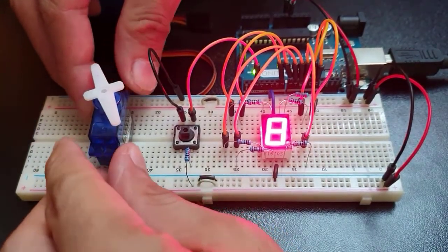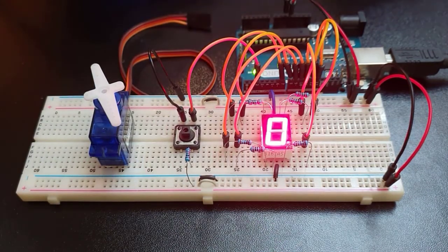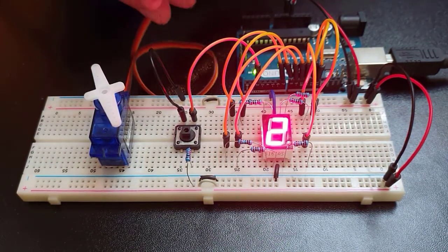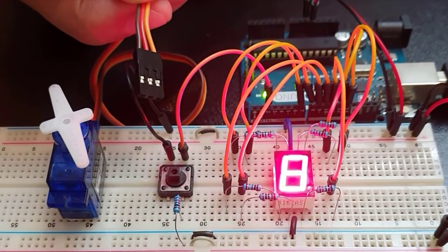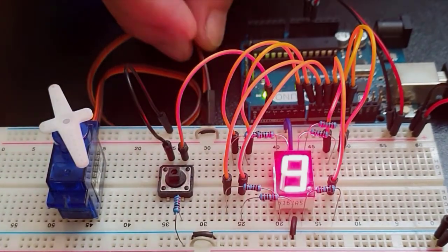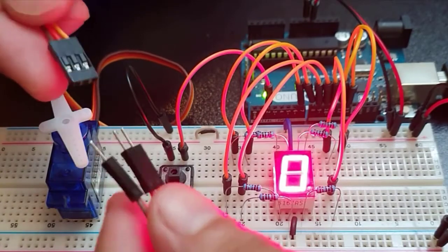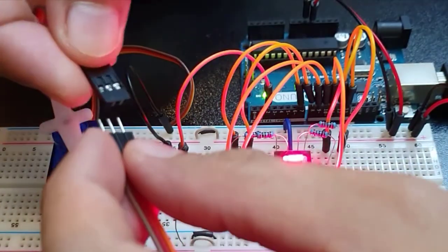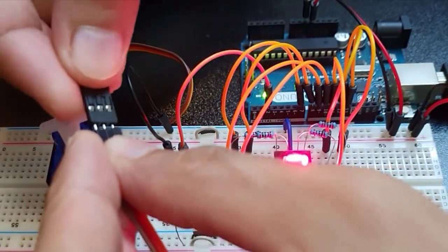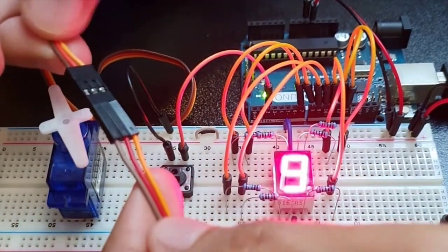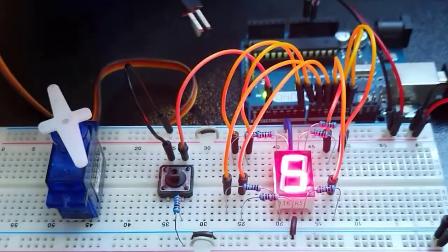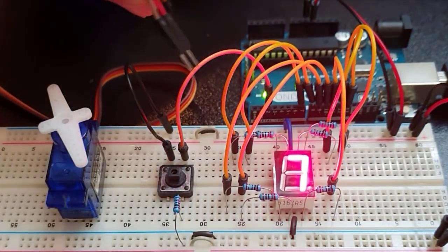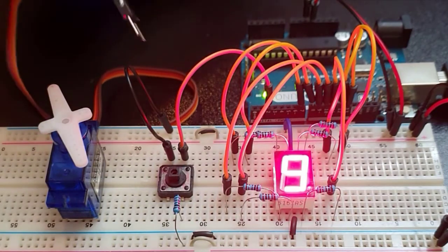So, how do we connect a servo motor to the Arduino? Wiring a servo motor is very easy because you only need to connect 3 wires: the power, ground, and the signal. The power wire is typically red and needs to be connected to the positive 5 volts. A microservo like this, SG90, consumes around 10 mA when it is idle, and 100 to 250 mA when rotating, so you can power it directly with the 5-volt output of the Arduino.